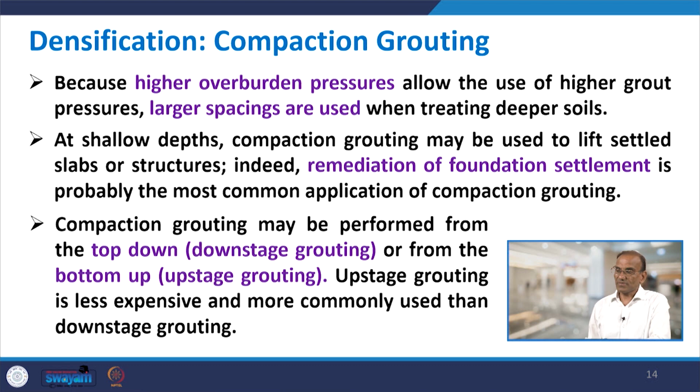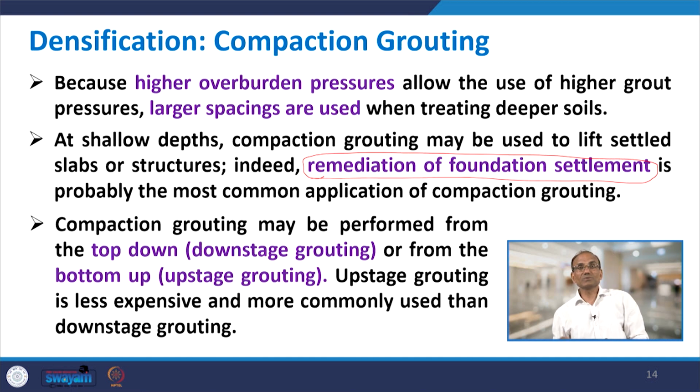Indeed, remediation of foundation settlement is probably the most common application of compaction grouting. Suppose your foundation settlement is not within the permissible limit. So, many times we use compaction grouting for that.